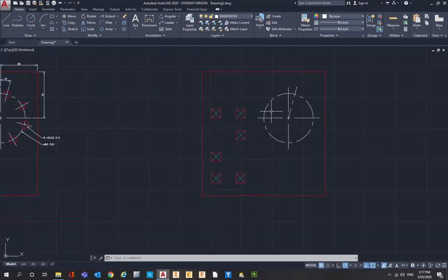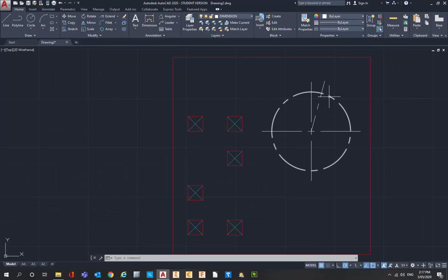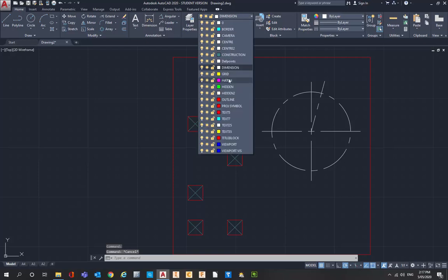Over here I've set up the construction we'd need. I've come in 60 and come down 75 to give us our two center lines here. I've also already drawn the 80 PCD, or pitch circle diameter line, and I've also already drawn the center line inclined from the vertical at 15 degrees. It's the intersect point between the circumference of our PCD and that center line that gives us the center point for that first circle. So I'll go in and draw that first circle.